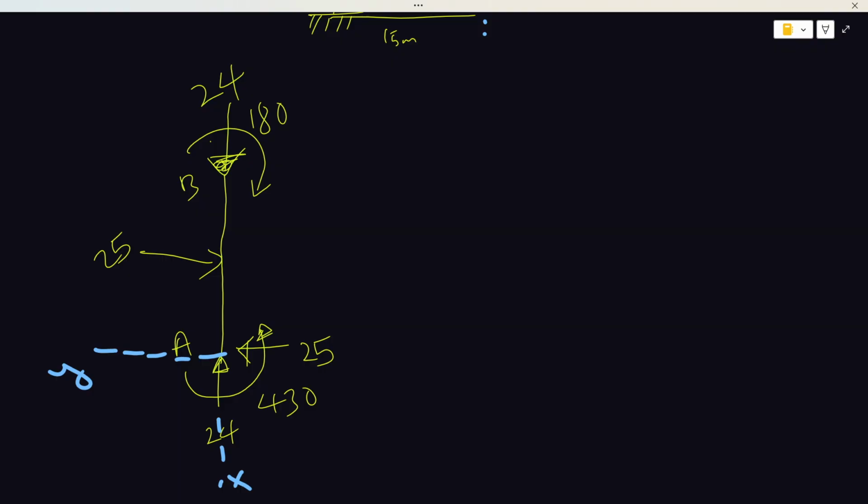So it means that if this is A, this is A, of course, and B. So it means that my shear force at A will be plus 25. I mean, the y direction, so that particular force acting in the y direction, positive. If you don't get it, you can tilt the member, you can make the member horizontal by tilting it in this manner. Then you understand what I'm saying, that, wow, this is actually plus 25.